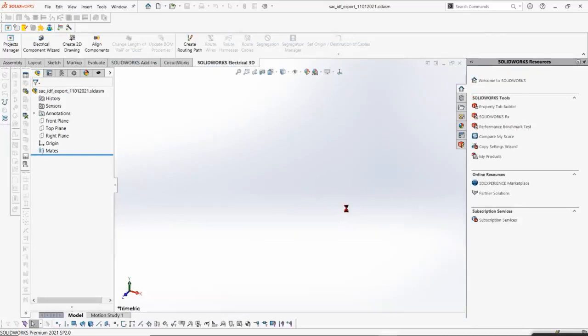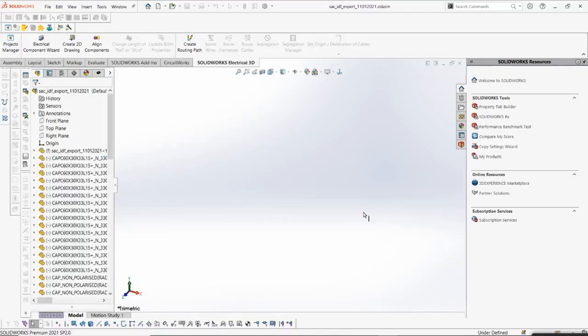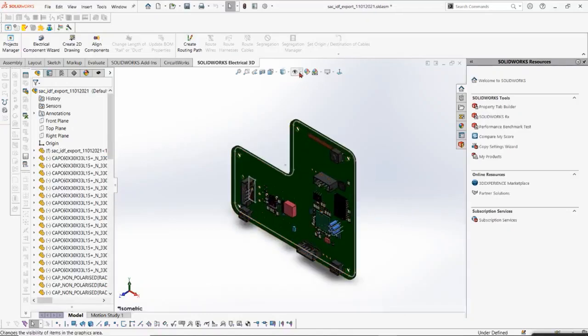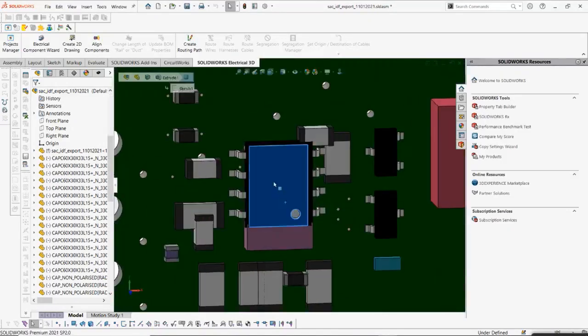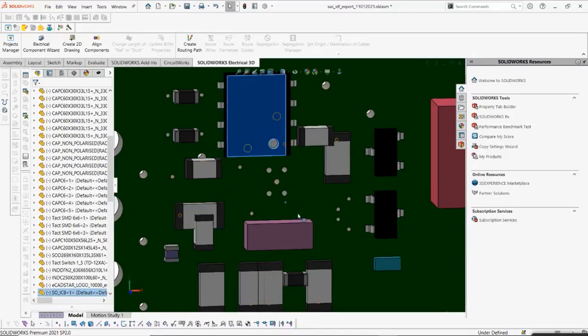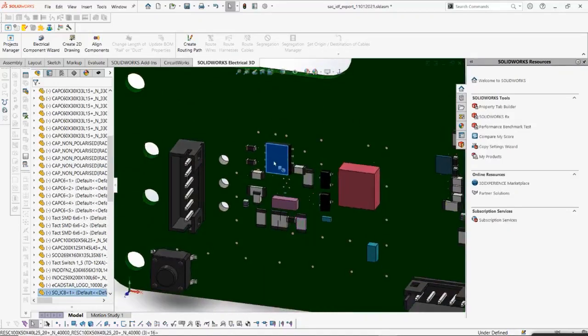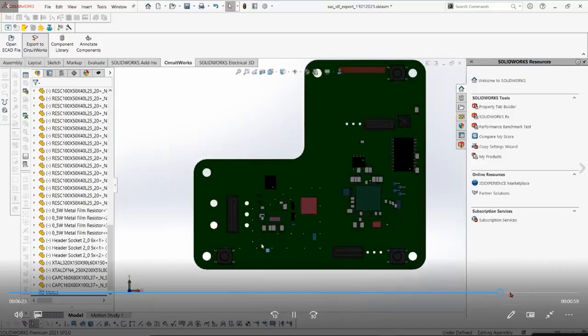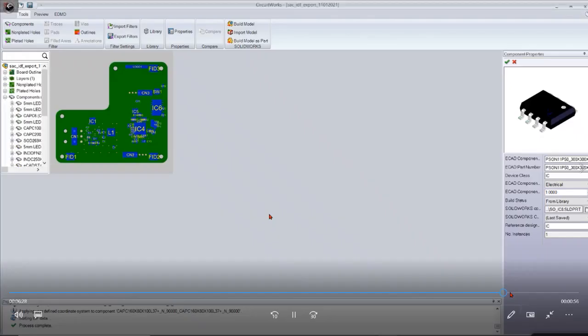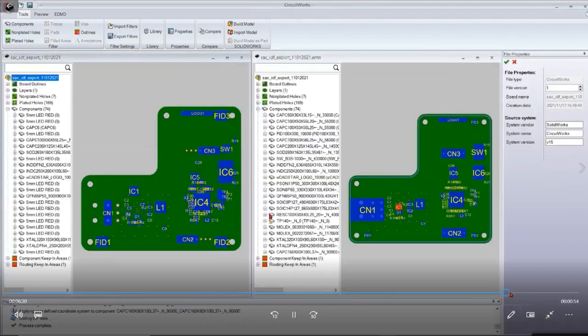In this way you can modify the existing components through Excel as well as by manually selecting a component and replacing the part file. You can move the component, change the placement, as well as export it into EMN, EMP format. Let's say I am ready with that model, and again I will go to export ECAD file.